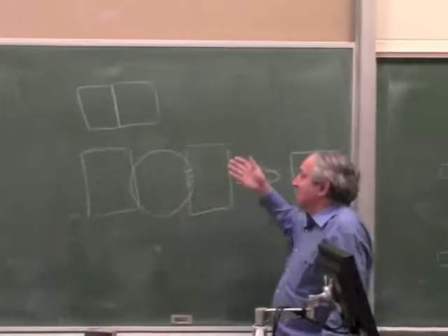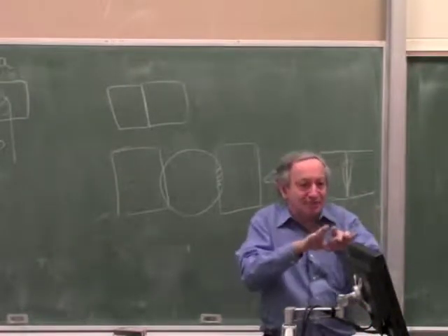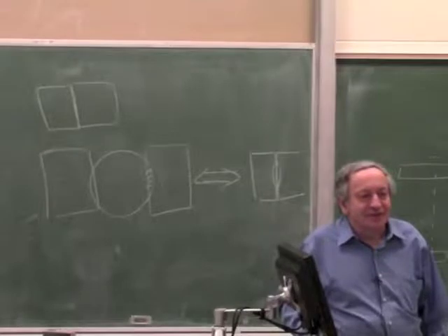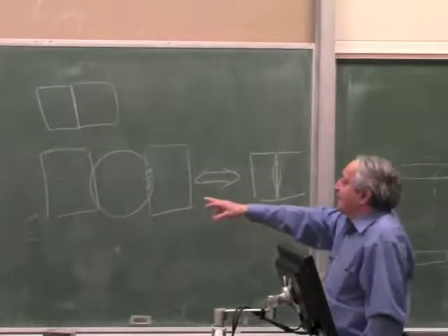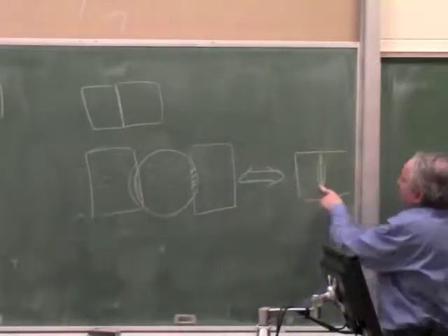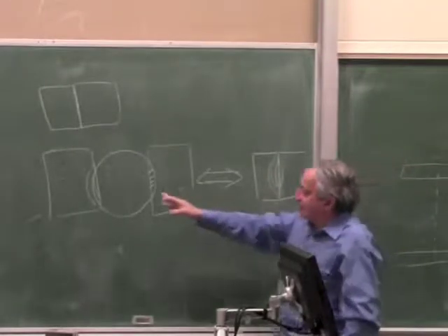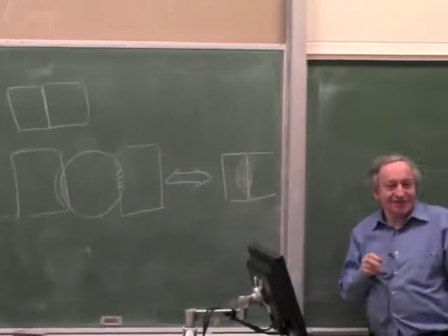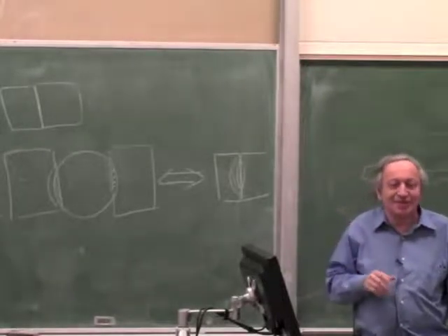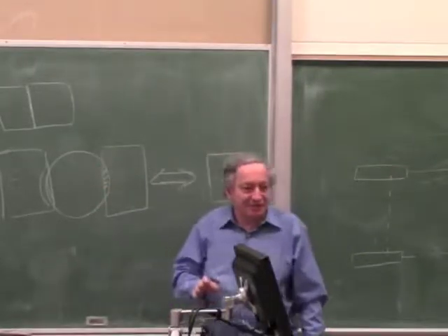The first surprising conclusion is that A doesn't matter at all, so you don't have to make the two detectors lithographically spliced to perfection, you can just stick them together. Yes? The size of D doesn't affect the linearity. No. Because think of this. If this shape spot moves a little bit, if you have the detector, you don't even know whether the light came from this or from this. It doesn't affect the linearity at all. Again, it's kind of counterintuitive. It takes a few minutes to think through it, and it doesn't matter at all. Obviously, you don't want to waste light, so you bring them together, but it doesn't affect anything.